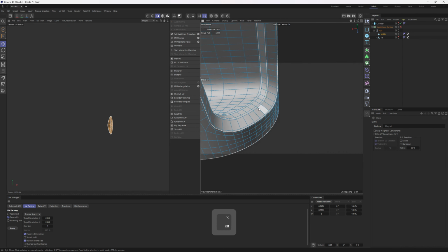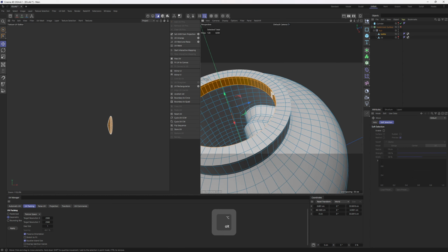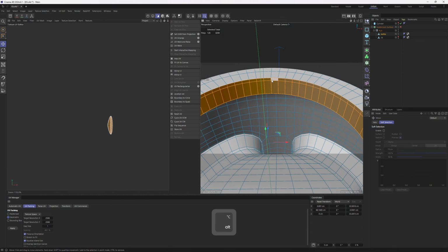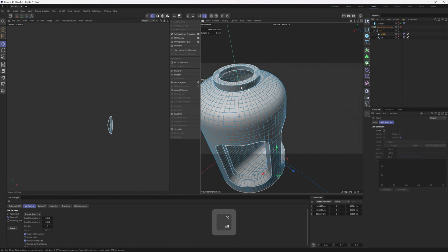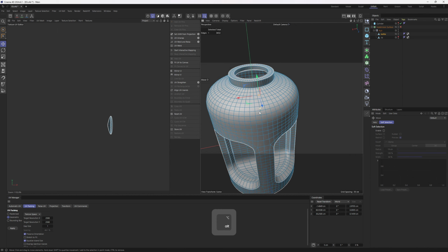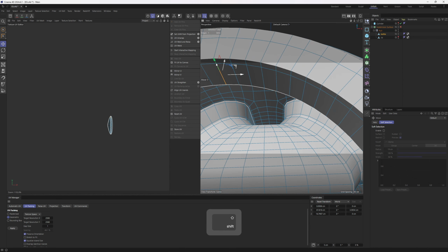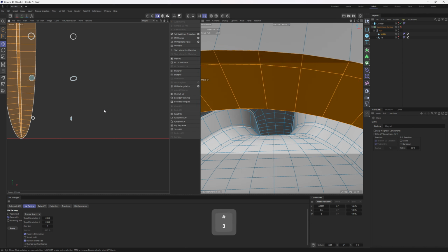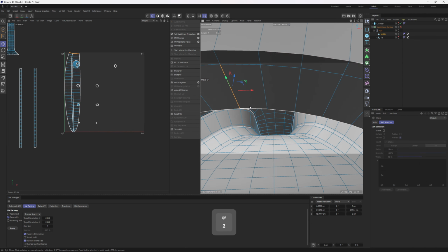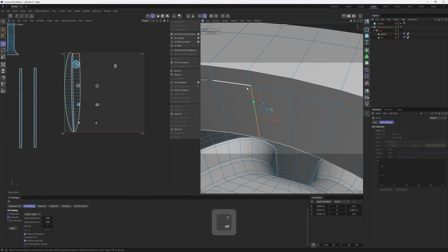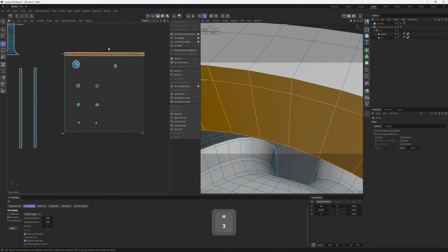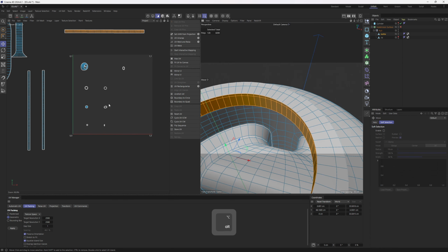Next up, this one. Again, this is a cylindrical shape. It needs an exit point. So let's follow these edges in the middle. Then click on UV Unwrap. It didn't work. Why? Because I skipped that edge. UV Unwrap, and here we go.